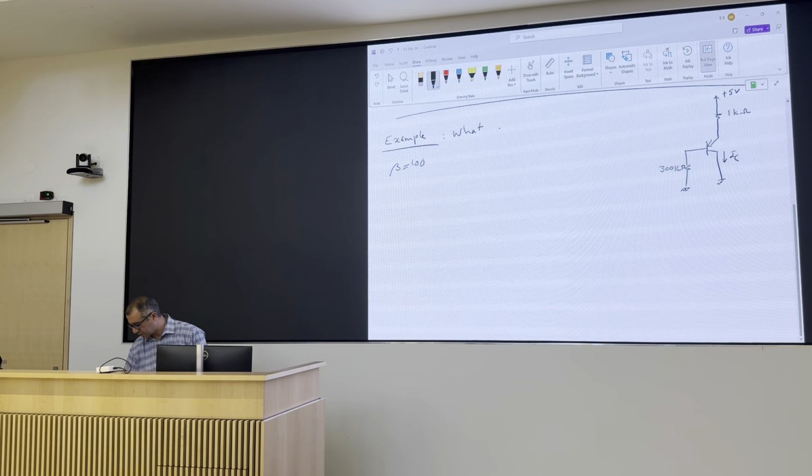So, or it is becoming forward biased. So you have some voltage drop across the base collector region, that diode, the base collector diode, which so far had a reverse current going through it. It starts to push a little bit of current in the other direction. So what happens is that as the transistor enters saturation,